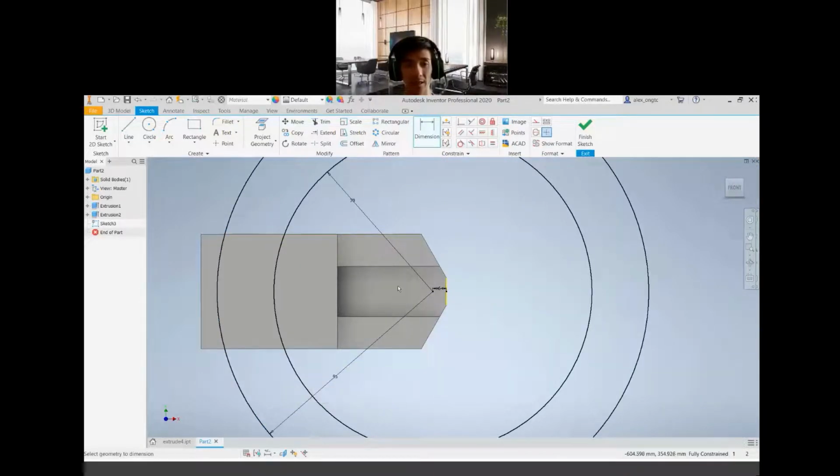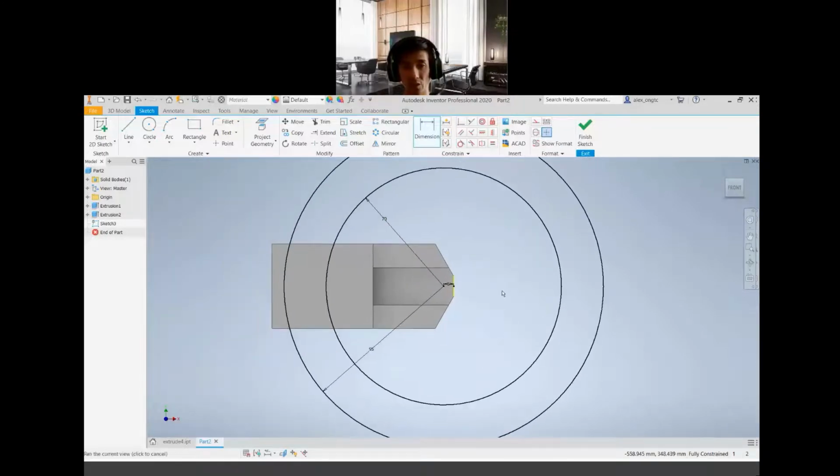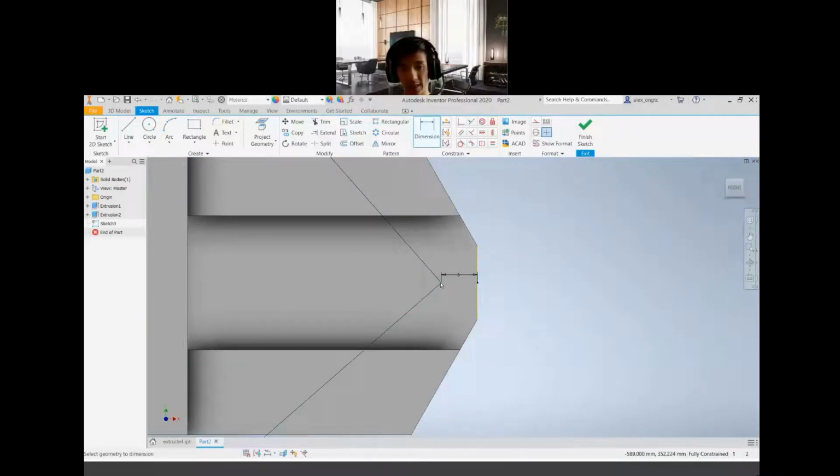Okay, so that's the dimensions of this drawing. I give you a minute to finalize it, especially the center point. The radius wise is very straightforward. I assume not much problem on this. Just on the center point placement here, you need to ensure they are at the same horizontal axis, and the distance here will be 6 from this particular line here.